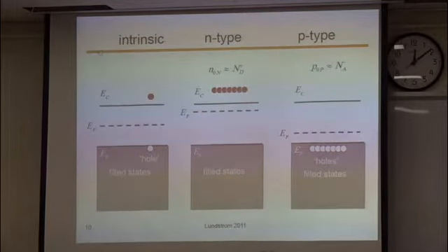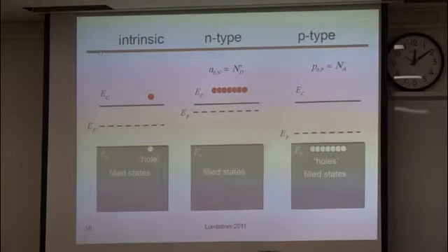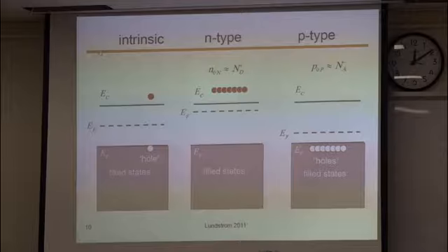N-type is the negative type, which is silicon developed by the dopant of phosphorus. Once the phosphorus is inserted into the silicon crystal structure, one more electron is added. So let's say we have one dopant of phosphorus, then one more electron will be inserted, and thereby the number of electrons will be higher than the number of holes.